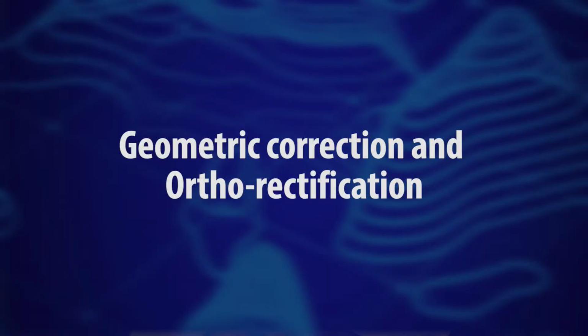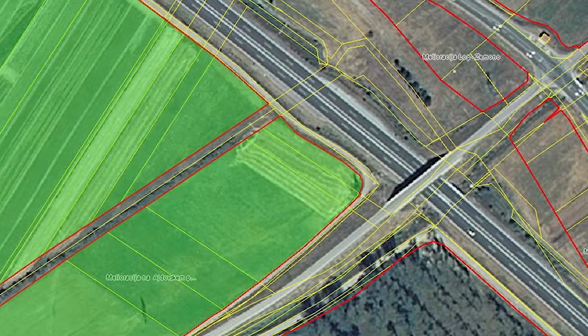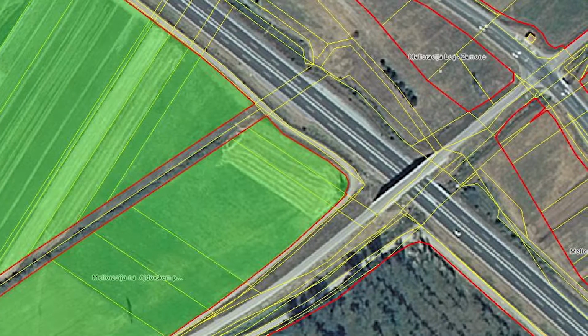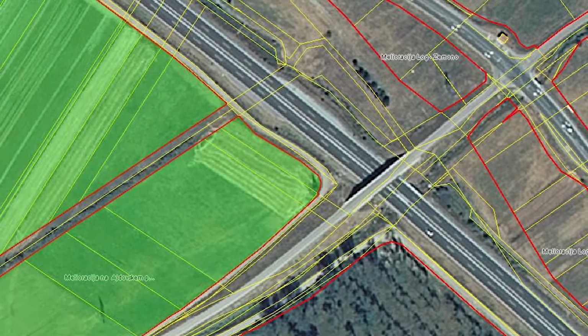Digital elevation models are being used frequently in such work. Geometric correction and ortho rectification. Images acquired through remote sensing show spatial displacements of objects and scale variations that relate to sensor orientation and topographic relief. Such displacements are removed in order to create a planimetrically correct, that is ortho rectified image, that is an image that has properties similar to a map such as consistent scale.